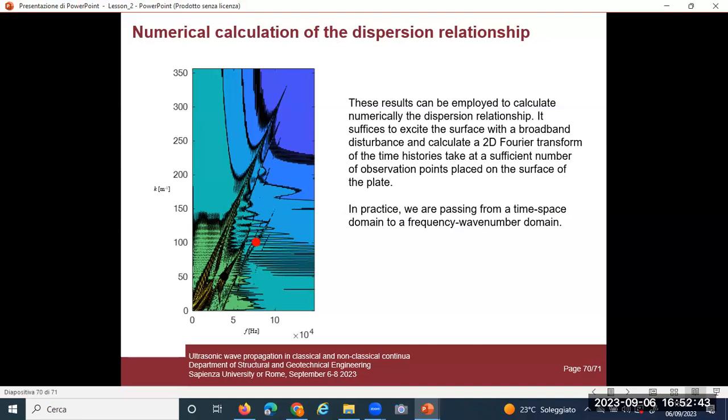It consists in applying a force which starts slowly in time. You've got to avoid abrupt changes. For instance, the case of a square wave is not really good, because if you don't put some damping, you are going to see a transient solution which will confuse everything. Otherwise, you've got to put damping. But you can use a very nice Gaussian function.